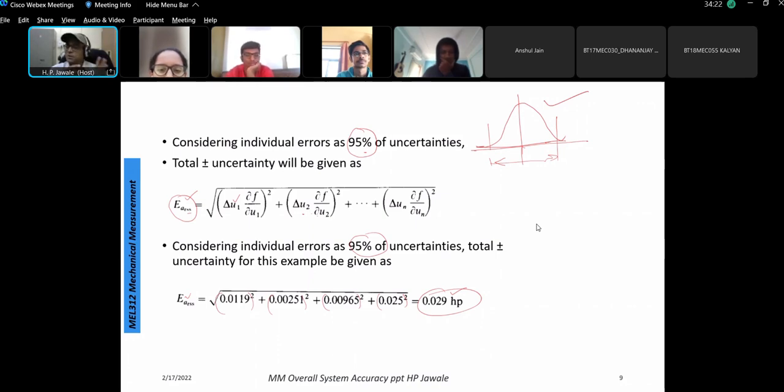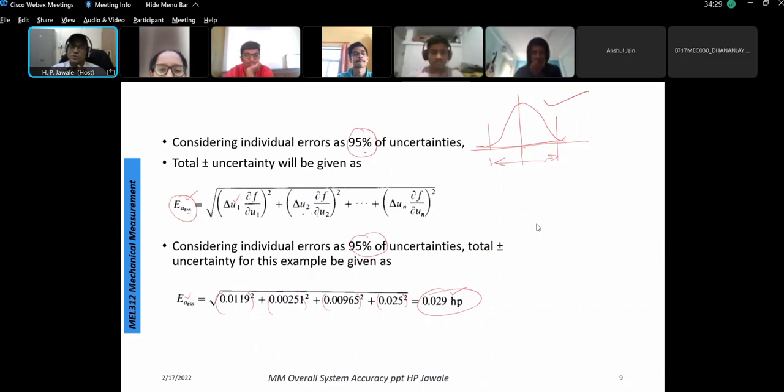For length measurement, earlier suppose I use a vernier caliper, but my experimentation is giving a constraint that the total uncertainty should not be more than 5% or 2%. In that case, I must know what shall be the accuracy of my device for length measurement and the diameter measurement and so on. So to know this, what is the maximum permissible error that our instrument or the measurement system for the particular entity measurement is to be taken, can be found out by the other approach, the reverse approach of this. You try to understand this.